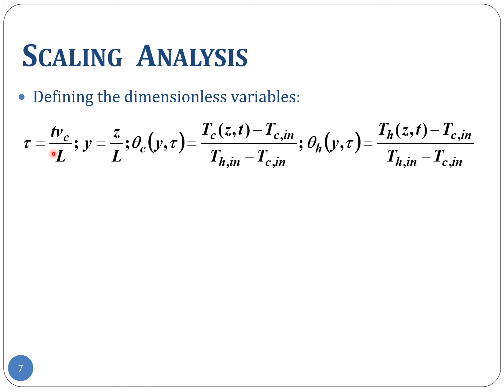And this you may have studied in your chemical reaction engineering course, right? So then come the dependent variables, which are basically the two temperatures, hot fluid temperature and cold fluid temperature. Now, if we look at the temperatures, what I've made use of here is our understanding that the driving force for heat transfer is the temperature difference rather than the temperature itself, and therefore it's perfectly all right to define a dimensionless temperature, but here what I've defined is a dimensionless temperature difference.